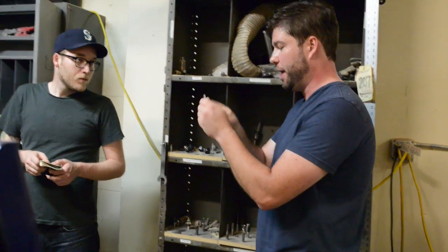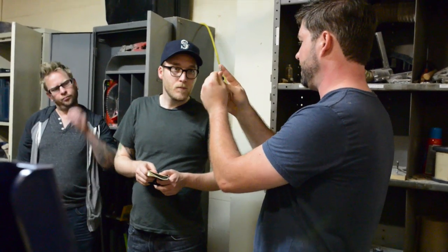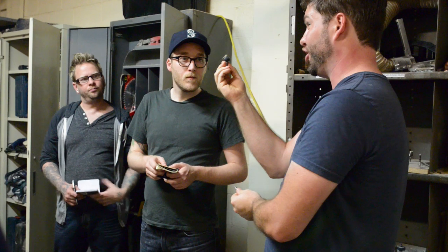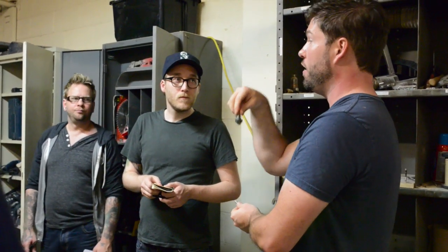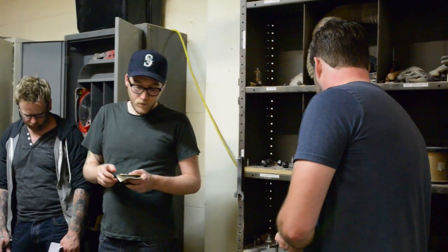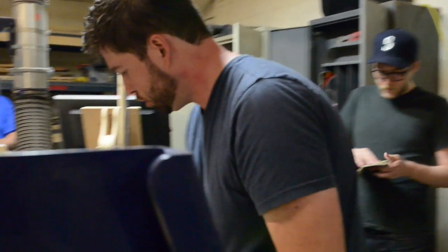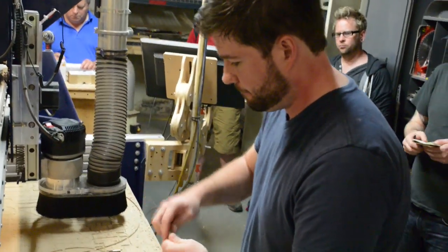I think this bit is kind of gnarly, but it comes to a 60 degree. This actually comes to a perfect 90 degree. You can definitely use this, but you've got to make sure that you told the program that you're using the 90 degree V-carving bit. So we're going to use these 2 different bits. I'll put all these away and show you how to install it.